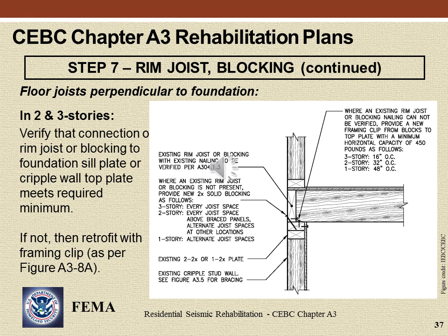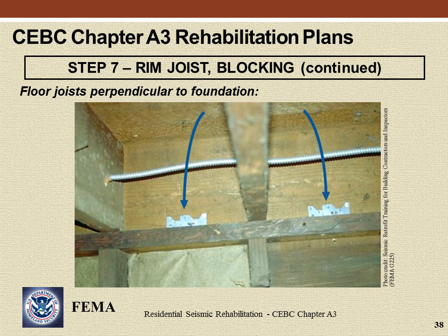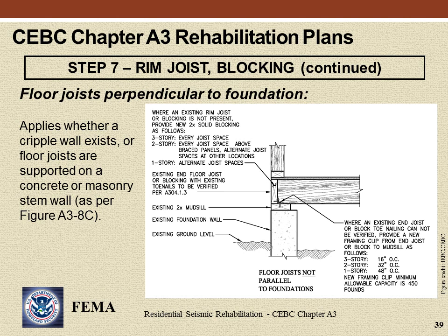A3-8A. It is often difficult to locate existing nails, if they are present, because some or all of them may have been driven from the exterior face of the wall. As a result, it is common for new framing clips to be provided. Where floor joists are perpendicular to the foundation, the photo shows clips installed from top plates to blocking as an alternate to toenails. The angle clips shown are equivalent to the generic clip shown in the figure.